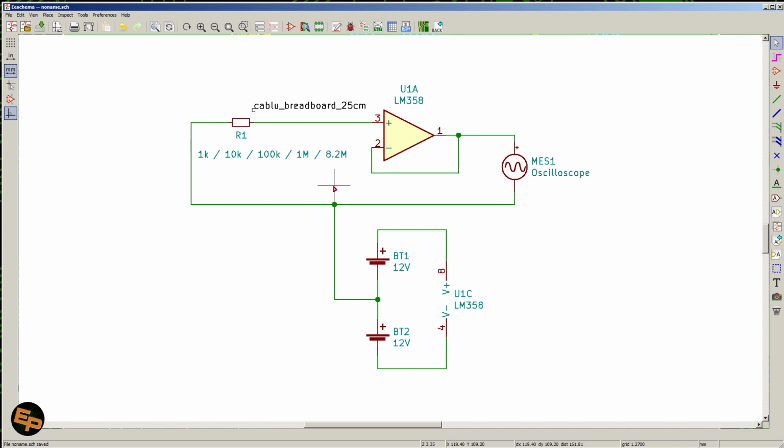Perhaps we can use coaxial cable or a shielded cable connected at both grounds, both from the previous circuit and to this circuit's ground. Or we just have to live with the extra interference that gets added on top of our signal, if that's possible.